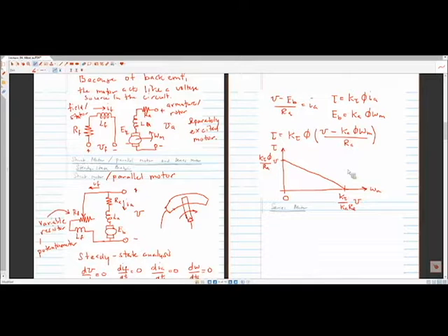Basically what it does is, going back to my circuit diagram on the left-hand side here, this is a constant voltage. I haven't changed the voltage of this analysis at all. What we have changed is the motor speed. So if the high side of this back EMF increases because we're spinning faster, that means the voltage drop across this resistor is smaller. The current going through that resistor, therefore, is going to be smaller. So then the torque, which is proportional to current, becomes smaller. So it's an electrical limitation, and this exists in all motors. This is not unique to DC motors at all.